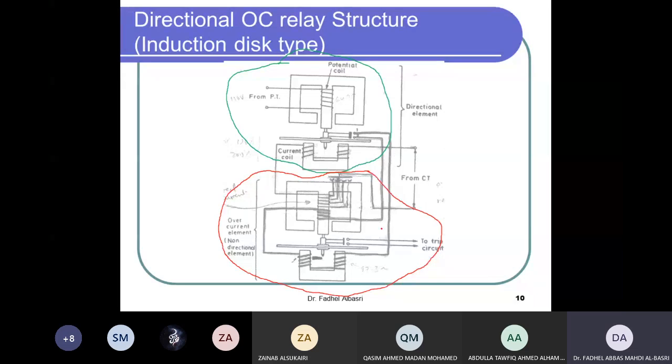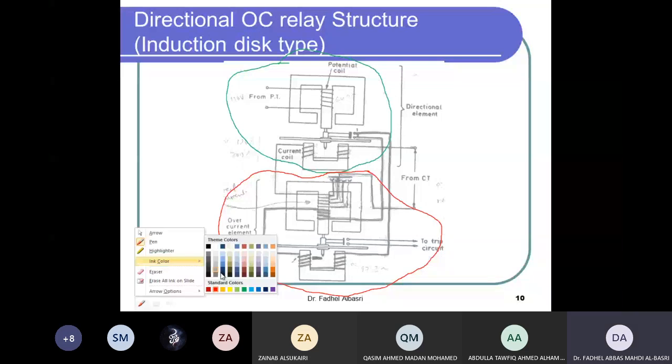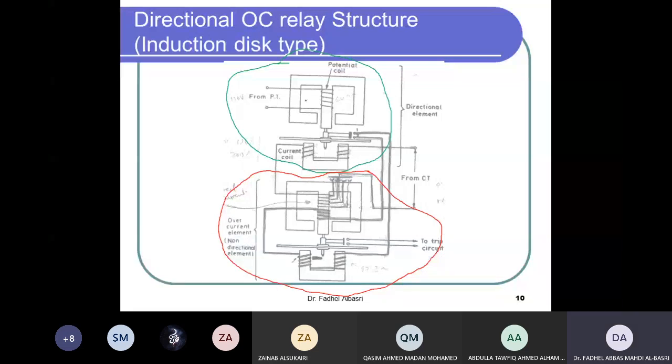So in the directional overcurrent relay, for the directional relay, I have a voltage reference from a VT, from the VT inputs as a reference, and the current will come from the CT, somewhere here, which comes to these two points.